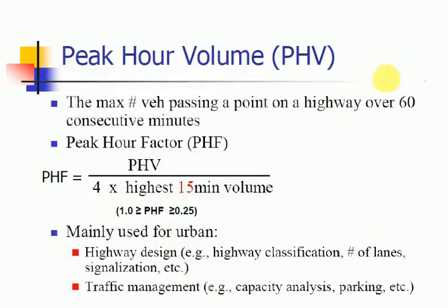Whatever value you are getting is used basically for the approximation of the peak hour factor. If it is close to 1, say 0.95, 0.98, it is basically for congested conditions, while as the value reduces, the congestion also decreases.